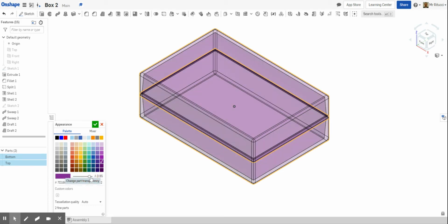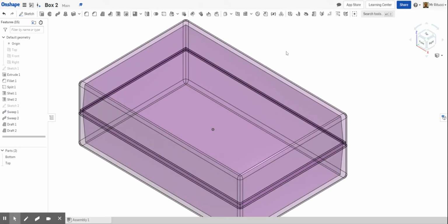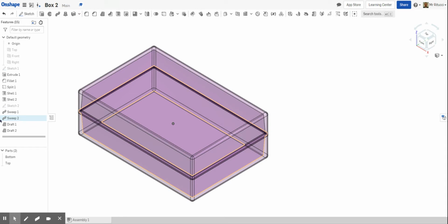So that lesson today has talked about 4 features, 4 new tools that you've learned how to use. So firstly, the split tool. So splitting an object in half, but making sure that you have drawn on either side of the work plane, allowing for the work plane to split in half.